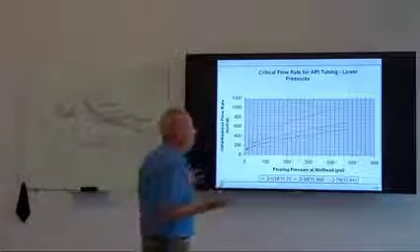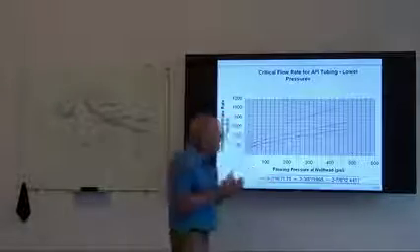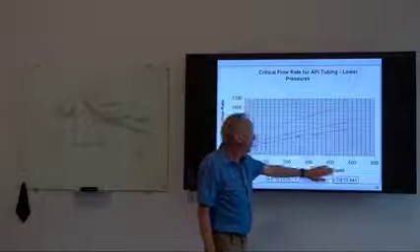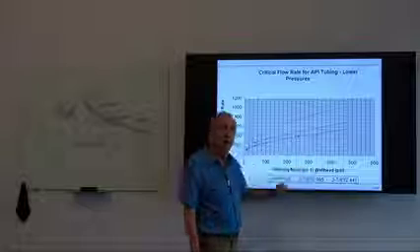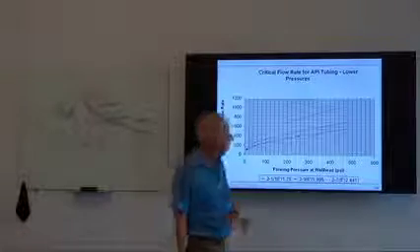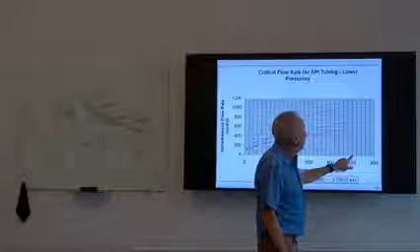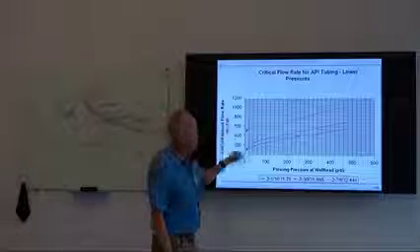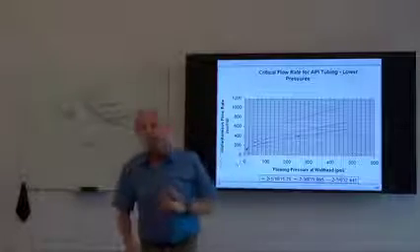What about downhole? What if downhole we had a much higher pressure? So instead of saying just at the wellhead, it's really a function of this flowing pressure. What if my bottom hole pressure was 500 psi? Well, if I come out here and look at what that represents, we have about 700 MCF a day.